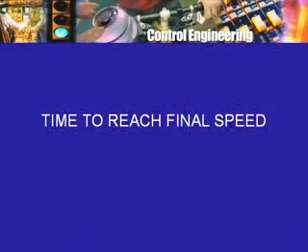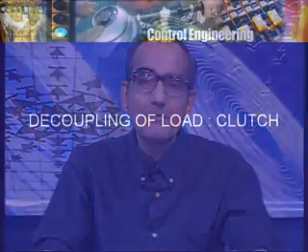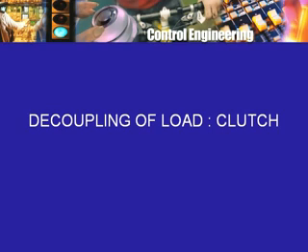Another important consideration will be, with the load on, how long does the motor take to reach the final speed? Because one would like the motor to speed up to the final speed as early as possible. In fact, again in practice the situation will not be that simple. The motor will be started without any load, that is, the load will be decoupled.